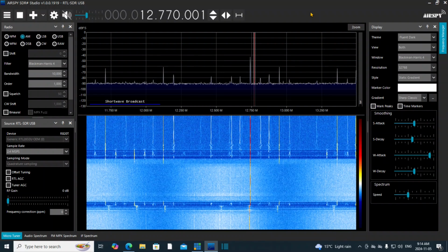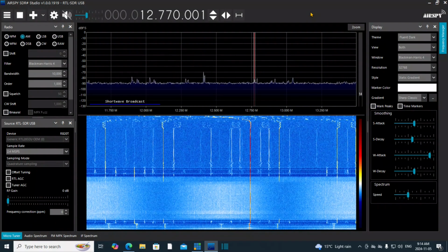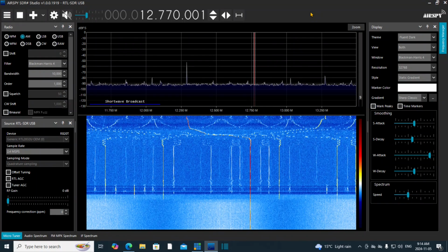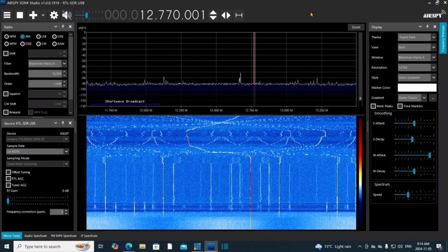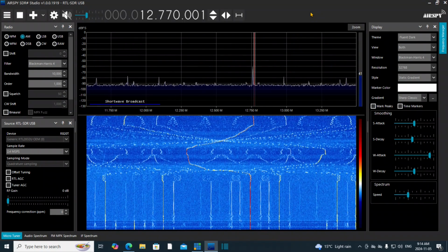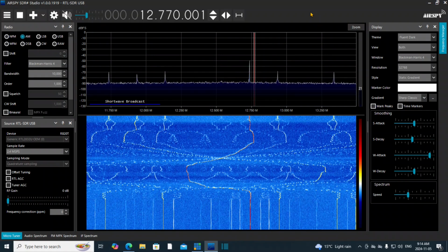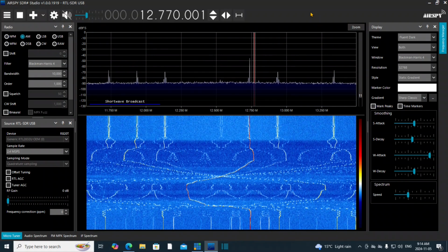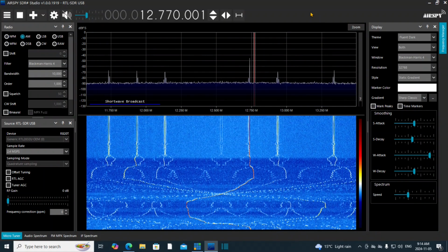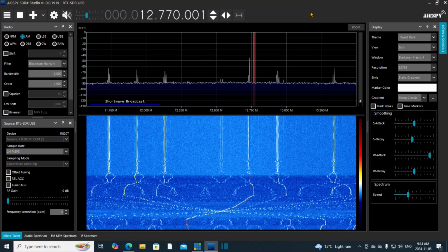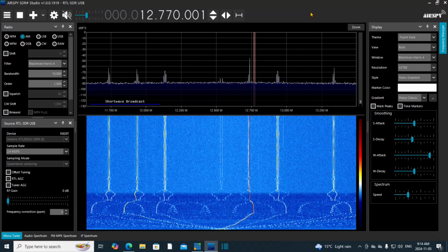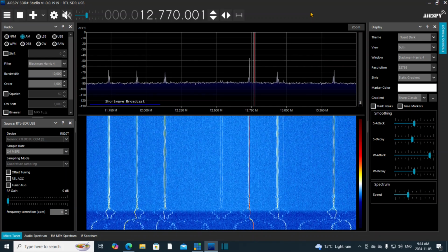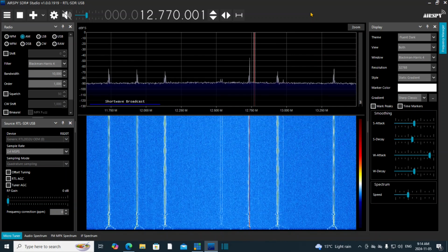Now I'm going to tune the radio a bit, and you'll see the local oscillator move rather rapidly. And if I stop here, it's about 12.75. Take off 450 and it's right around 12.3, which is roughly what the signal generator was sitting at when the radio picked it up. So that all makes sense. So there's a local oscillator.